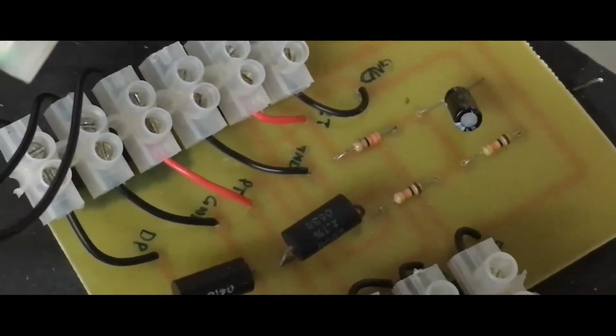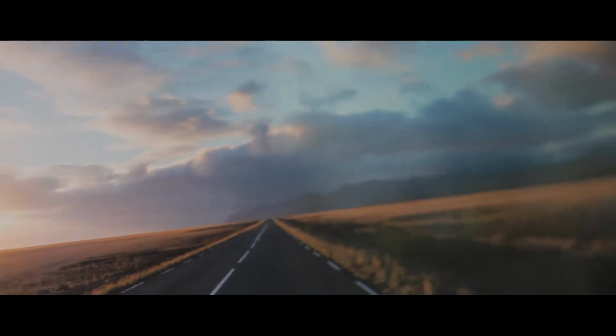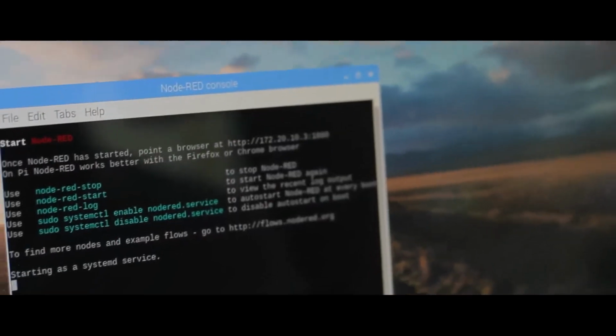For the next part, sensor data will be uploaded from the NodeMCU, an open source IoT platform, to the MQTT server. This is done by using an MQTT broker on a software known as Node-RED, which is installed in the Raspberry Pi. The MQTT broker, in our case known as the Mosquitto, is installed on the same Raspberry Pi the Node-RED is running in.